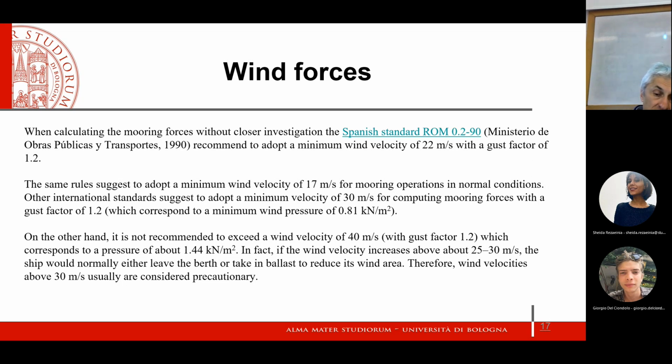If the body is rigidly linked to the land, then the action becomes less elastic. By the way, the springs have some elasticity precisely for this very reason, because a rigid connection would translate into mooring forces that are amplified.